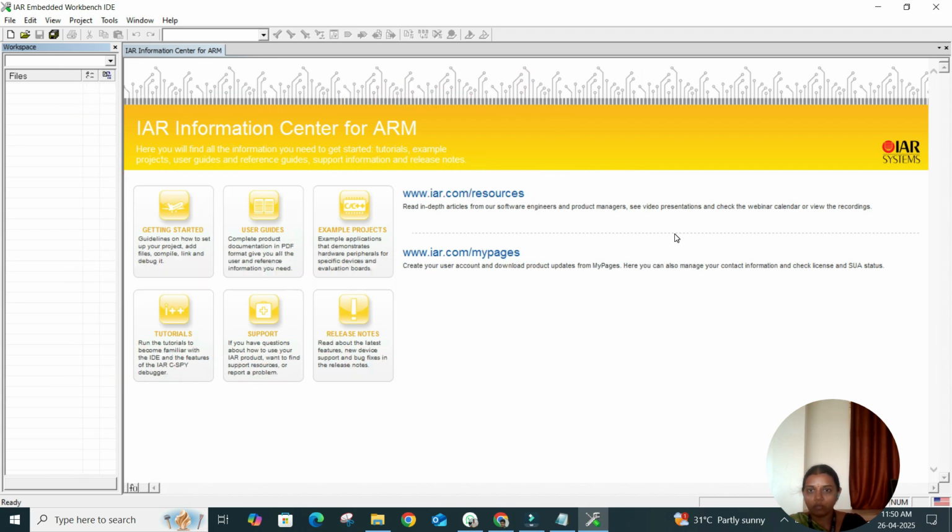In this video, we are going to learn how to compile and dump a program into the ARM LPC 2148 controller. We are going to learn how to compile a program using a compiler named IAR Workbench. So first, open IAR Workbench. The screen displays the IAR interface.